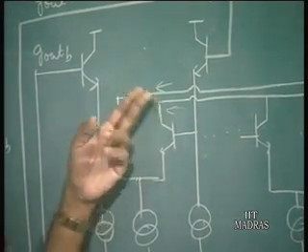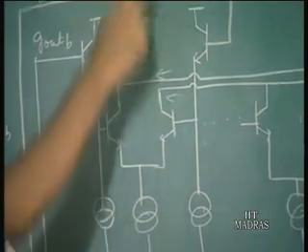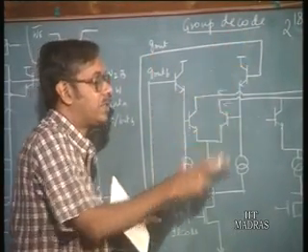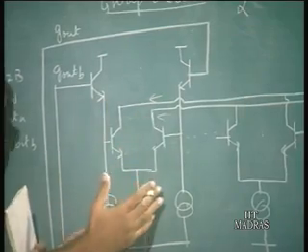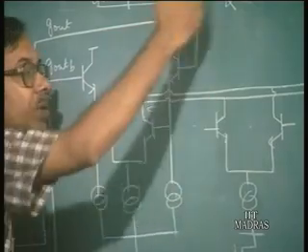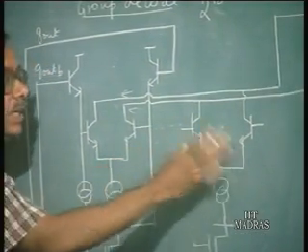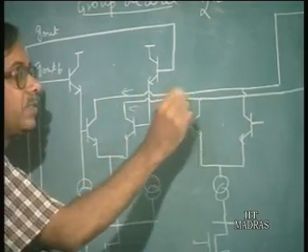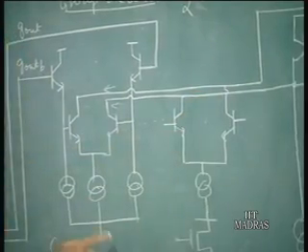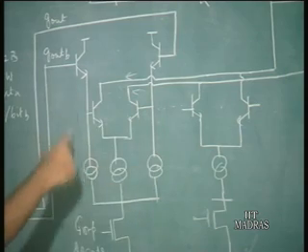So, this difference in collector current must be sensed. What we are also doing is a group decode. So, this output which you have is corresponding to a particular group of columns. So, you have 2 to the power 11 similar groups. This is the output say of another group, similar to this, and the collectors of all of them are connected to this same pair of lines here.